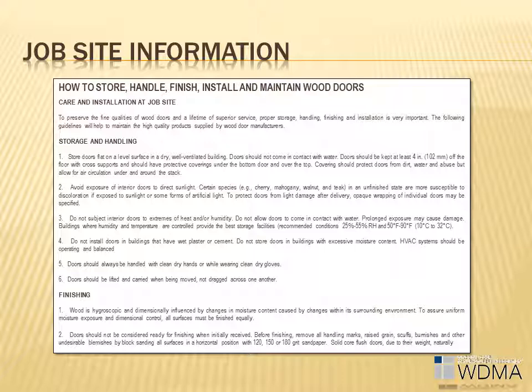Specifying a door would not be complete without information regarding handling of the door once it reaches the job site. ANSI WDMA I.S.1A includes comprehensive criteria on job site storage, handling, finishing, installation, cleanup, touch-up, adjustment, and maintenance. By adhering to these guidelines, job site contractors can help ensure that the quality of the product supplied by the door manufacturer is preserved.